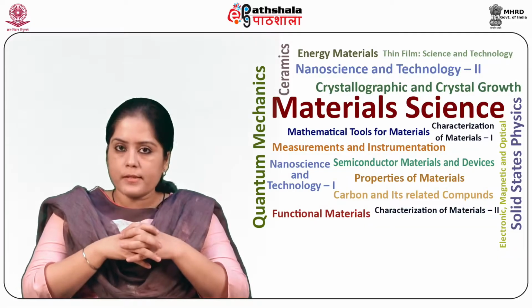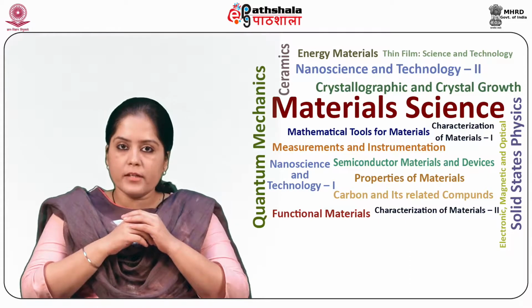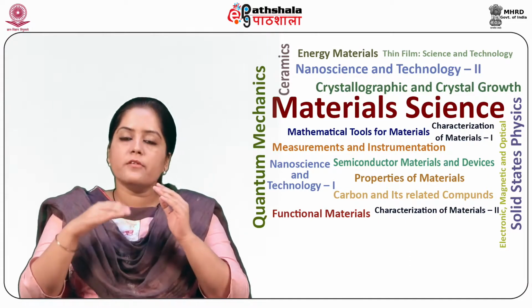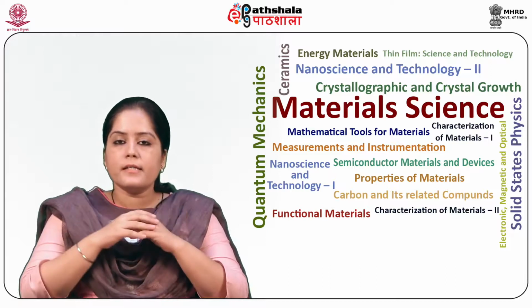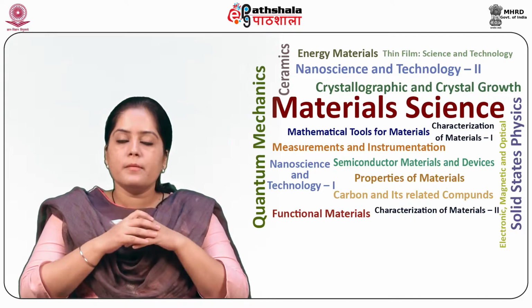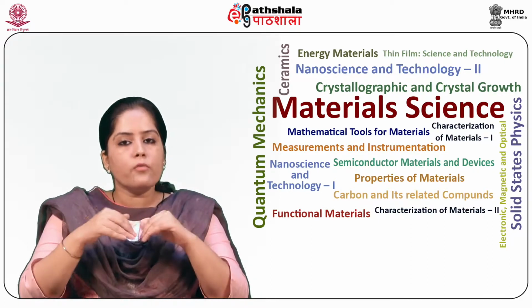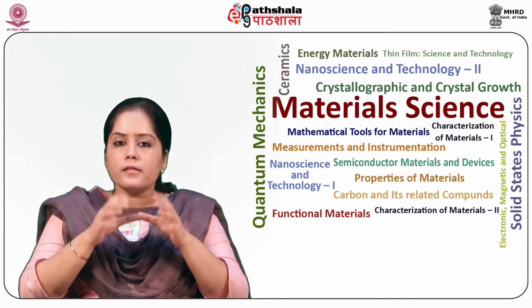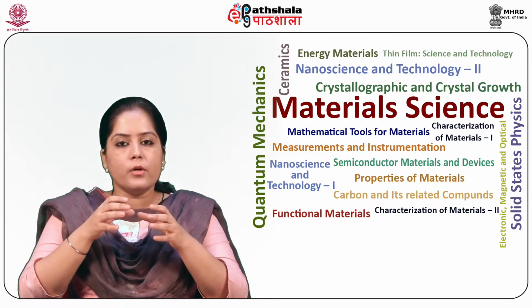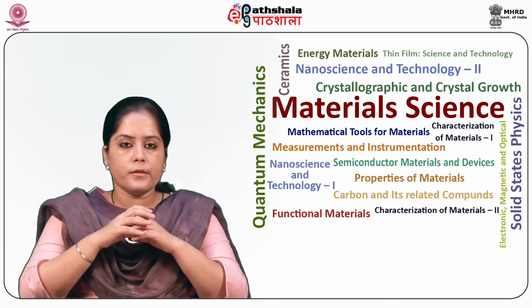AC plasmas. Since the effective resistance of dielectrics varies with the frequency of applied current, a capacitor coupled AC plasma sputtering system holds lower impedance and thus requires reasonable voltage for sustaining current through the target.